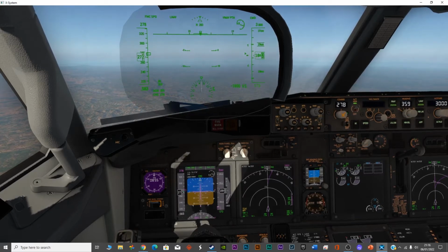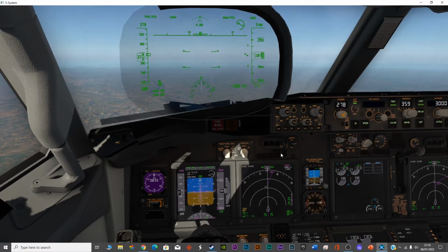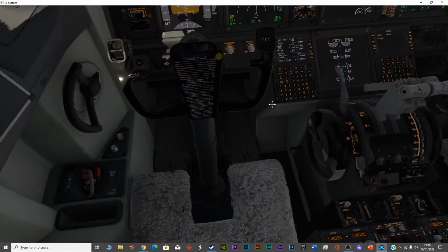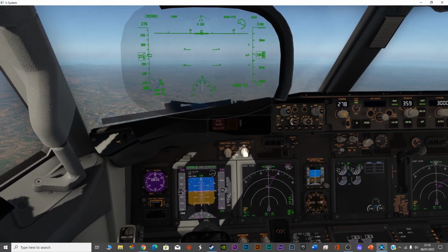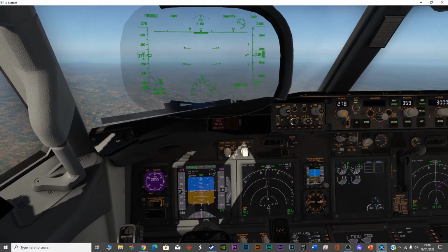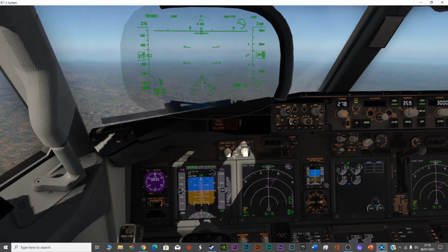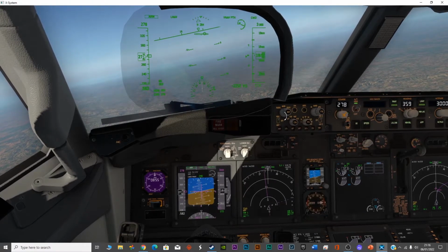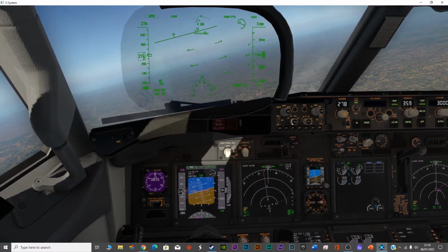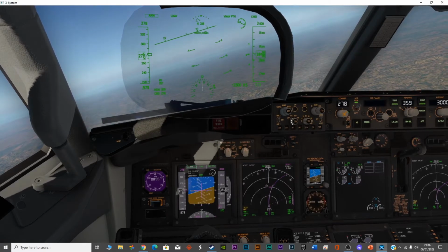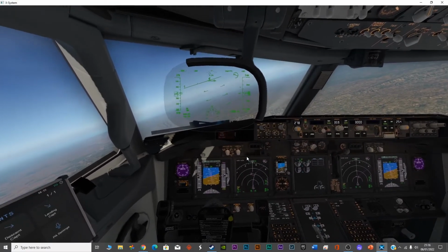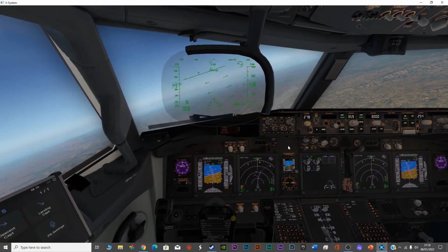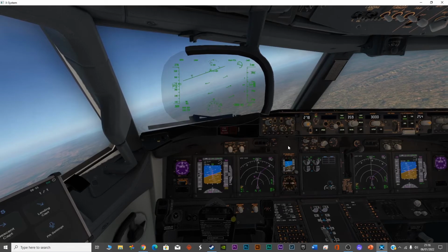Currently, I'm not entering the VOR information over here. But if you want, you can also enter the VOR information, and you can select the VOR, and plus from here you can select the VOR navigation and plus the approach navigation. I always forget to switch to the approach navigation over here in this option. So today, if I remember, I will switch to this option before landing so that I can see I'm properly aligned with the runway or not.